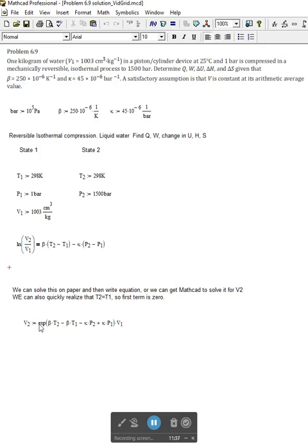So now V2, this is an assigning equation. V2 is calculated by this formula, and then if I want to print out the value of V2, I just type V2, so V dot 2, and then just the plain equal sign. A plain equal sign will give you the value of V2.